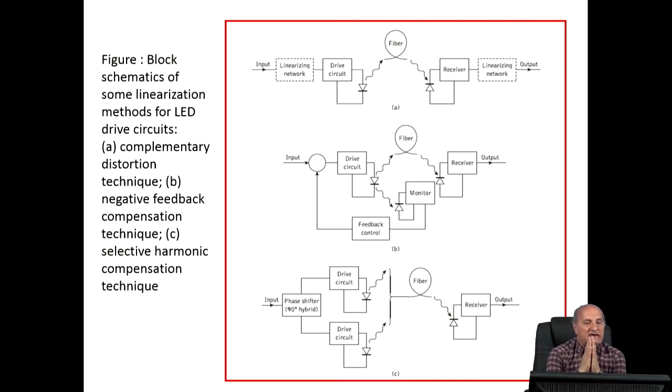At the receiver side, it is important to use the linearization, because at the transmitter the optical source is under control. The optical power of the modulated optical signal is high and clean, there is no noise, while at the receiver side, the received optical signal is low, embedded with noise, and the linear equalization should be used after the photodiode.